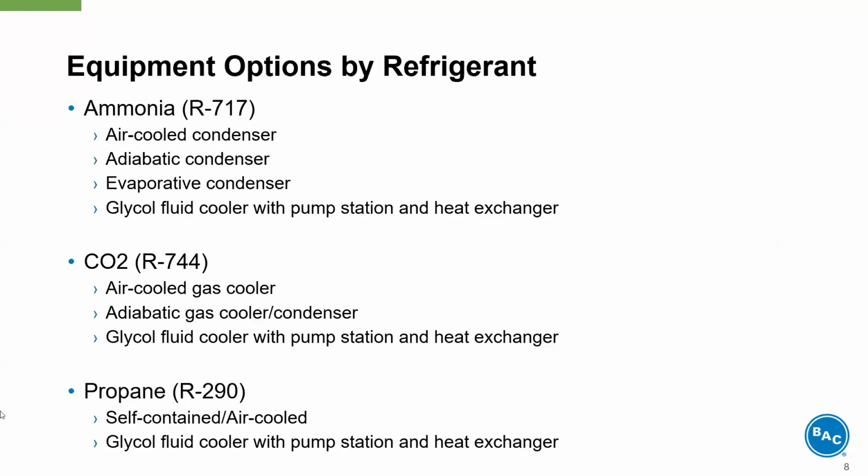And also we have the option of going with a glycol fluid loop using a fluid cooler with the addition of a pump station and ammonia to water heat exchangers or ammonia water cooled condensers.